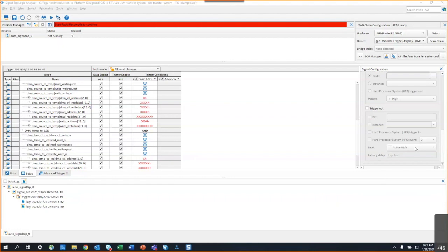So timing closure, looking at your SDC file, that might be something that you need to look at, because signal tap is functional only. So in situations like that, I would look more at timing, or start looking at timing if you haven't already. Thank you. I really appreciate it. You're very welcome. And we're having a timing closure office hours next month. So there you go.